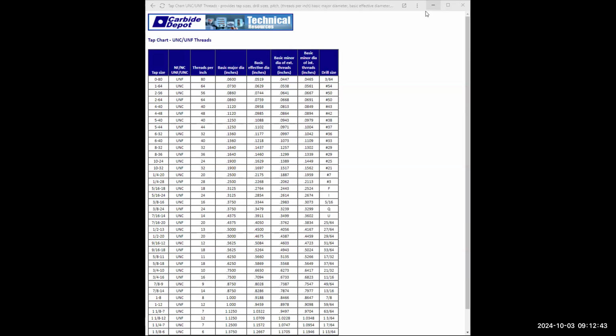Cut off your F8. And I like the arrow size. That's good. I'm going to click and I'm going to go across this way. You can hit F8 back on if you want to make it perfectly horizontal. Click, enter. Now it says enter the first line of text. Well, I'm going to type in, very careful here, percent C space 0.38.